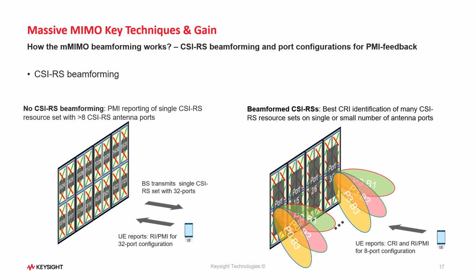On the right side, we have the example with the beamformed CSI-RS. And in this example, the base station is using 2x2 subpanel antenna array to form the CSI-RS beams for each of the CSI-RS antenna ports. And here, for example, we saw 3 beams. In practice, there can be higher number of CSI-RS beams transmitted by the base station.